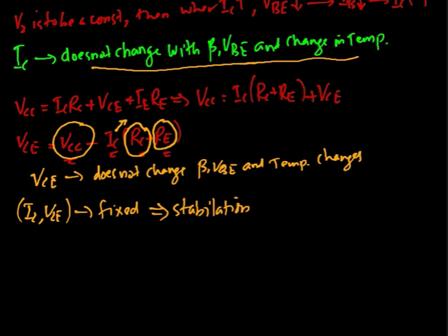But we have alternatively mentioned that stabilization has been obtained by the introduction of the emitter resistance RE. We have to ensure that a quantitative measurement of this stabilization is achieved through calculating the stability factor of the circuit. So now let's try to obtain the expression for the stability factor for the circuit.